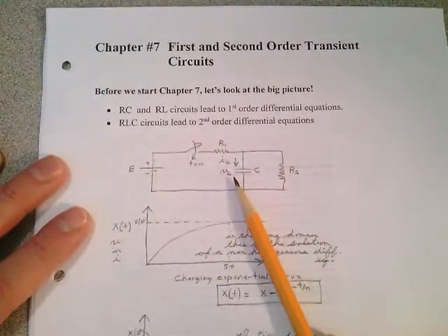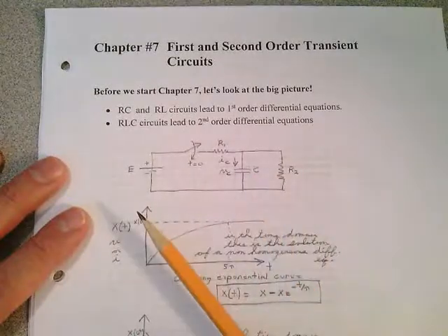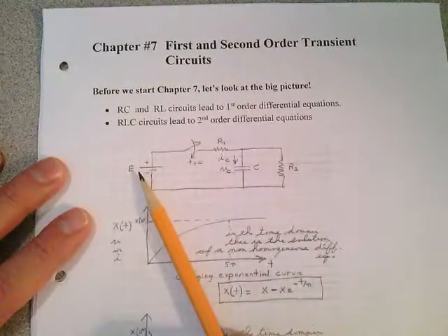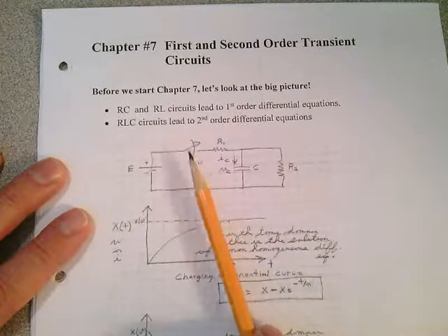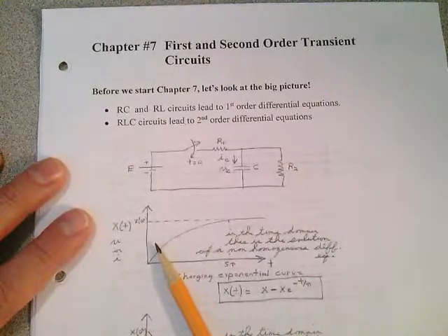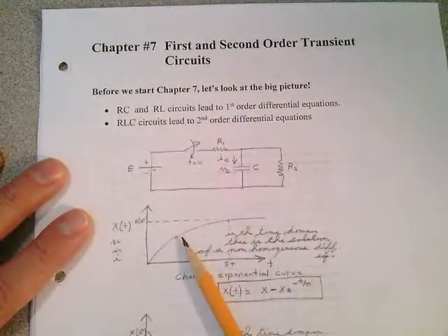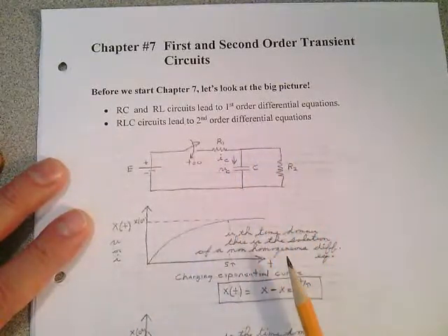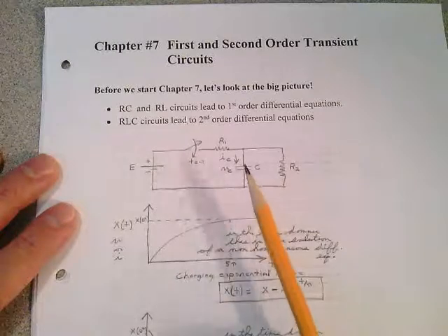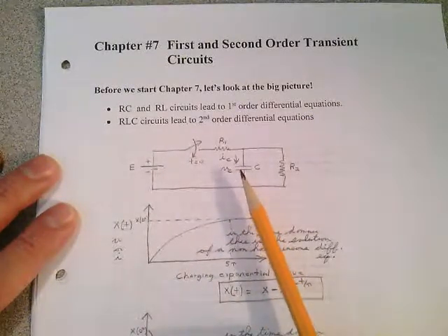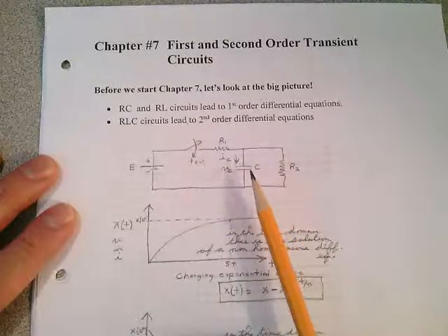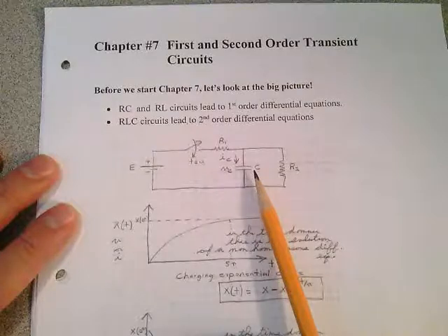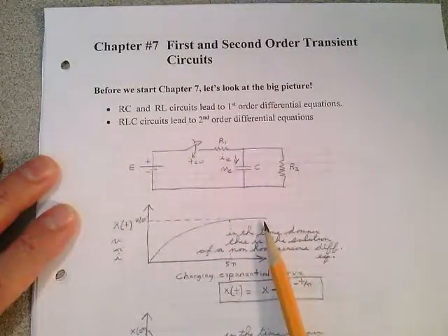I have a first order circuit here. Rather than an inductor and a resistor, I have a capacitor and a resistor. I have the source of EMF over here, and I have a switch. Now normally that switch is open. But at t equals 0, we're going to close that switch, and we're going to find out what characteristics of voltage and current are placed on this side of the circuit. Well, the values of voltages across or current through a reactive element have these types of response in a first order system.